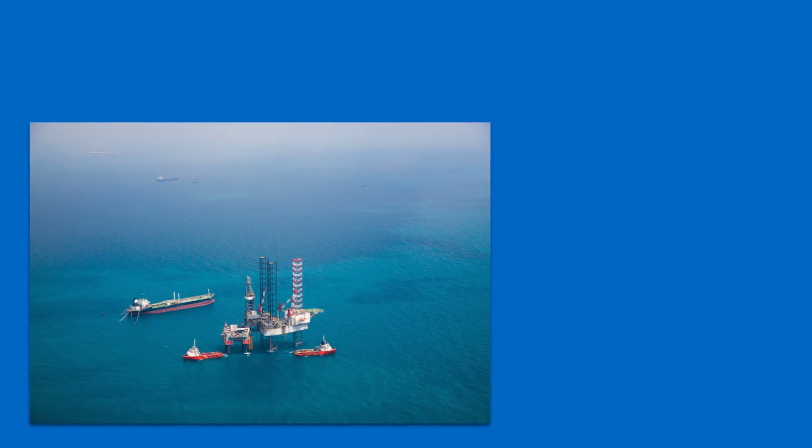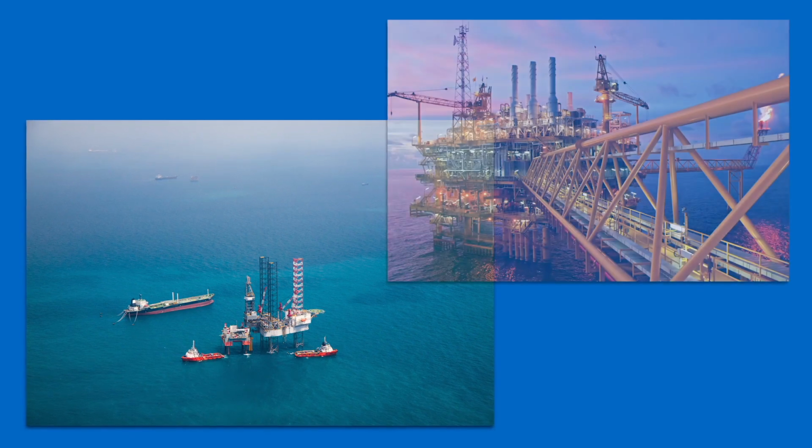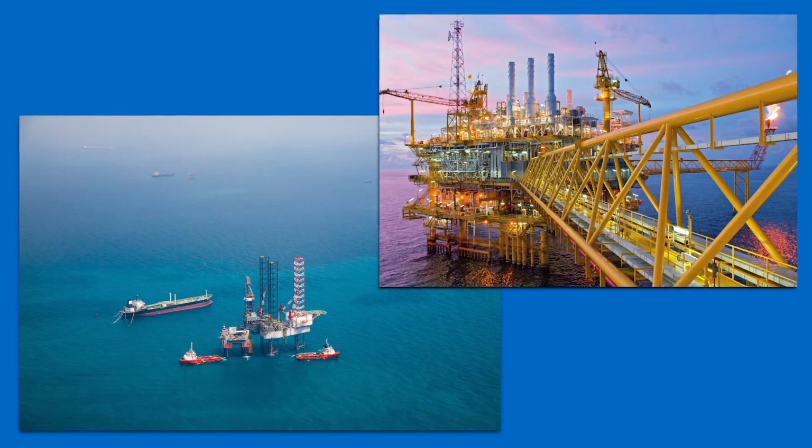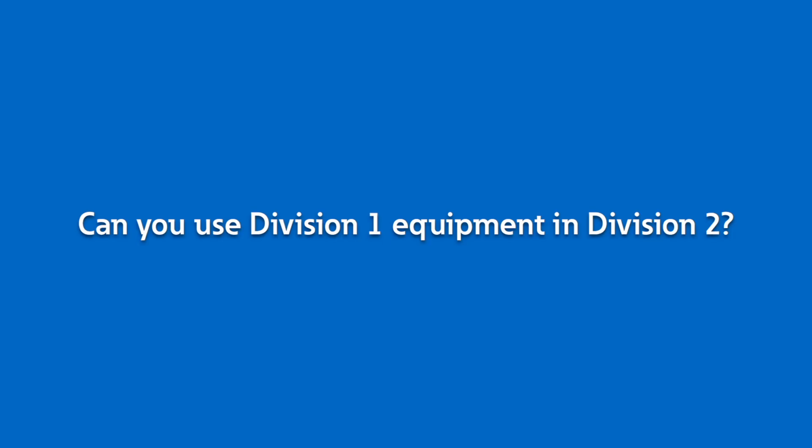In the Gulf of Mexico, we have some floating assets, like drill ships, that use IEC 60079. The NEC 505 code we use in the US is a variant of the IEC 60079. NEC 505 class and zone seems to be growing more popular than NEC class and division, certainly in the Gulf of Mexico.